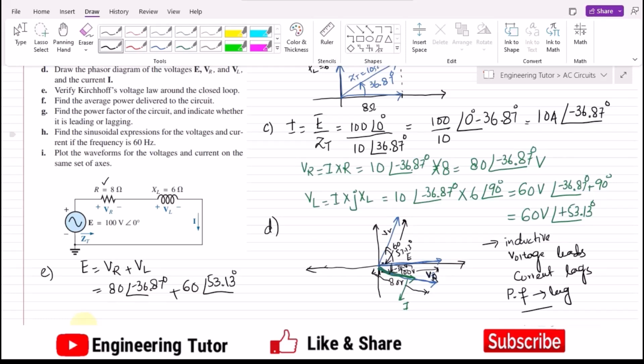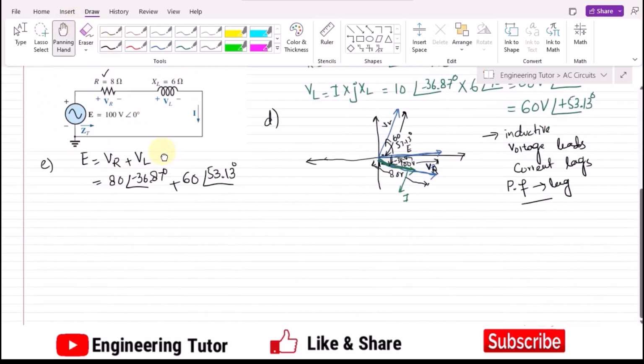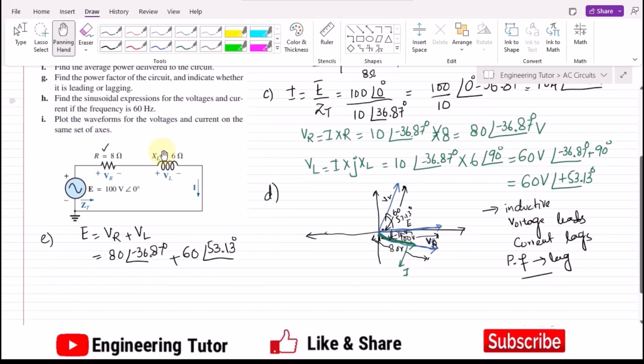Now in order to do it, let me add them together. If you are doing it manually, you may proceed using two methods. In the first method, you convert these quantities into rectangular form, then perform the addition, because for rectangular quantities, addition and subtraction is the most feasible operation. After that, once the real and imaginary components have been obtained, you may convert back into polar form.